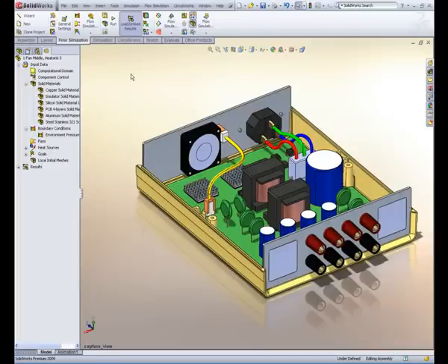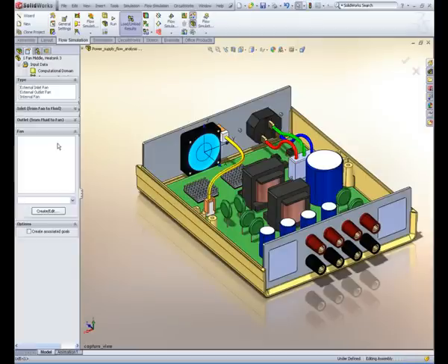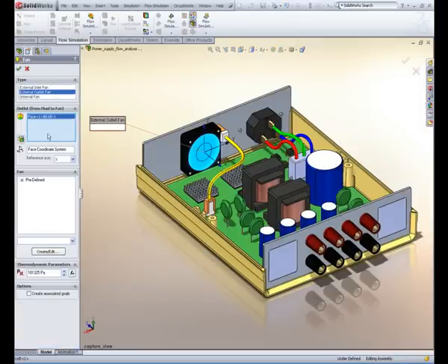However, rather than specifying atmospheric pressure, we want to suck air through this face and back out into the room. SolidWorks Flow Simulation allows us to select predefined fans from the built-in engineering database. So here we will choose an external outlet DC fan for our application.